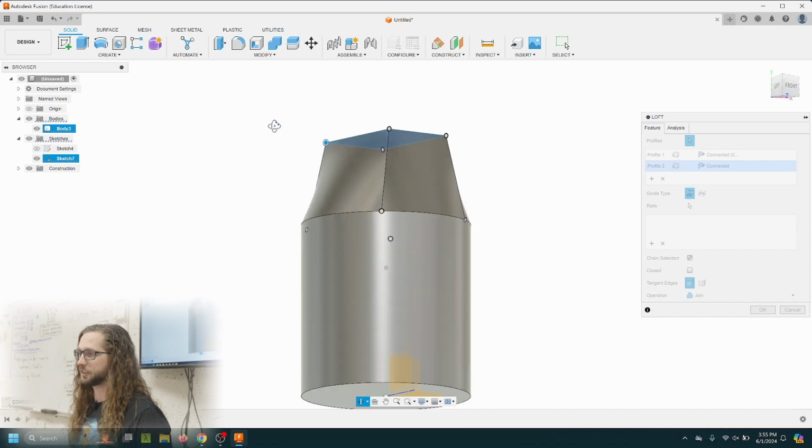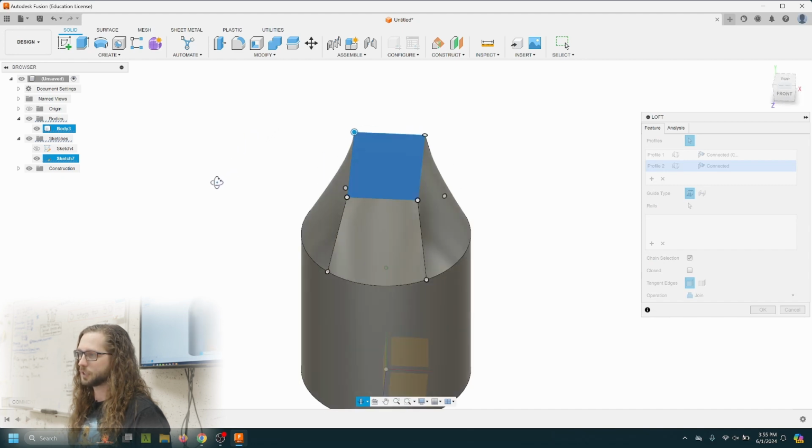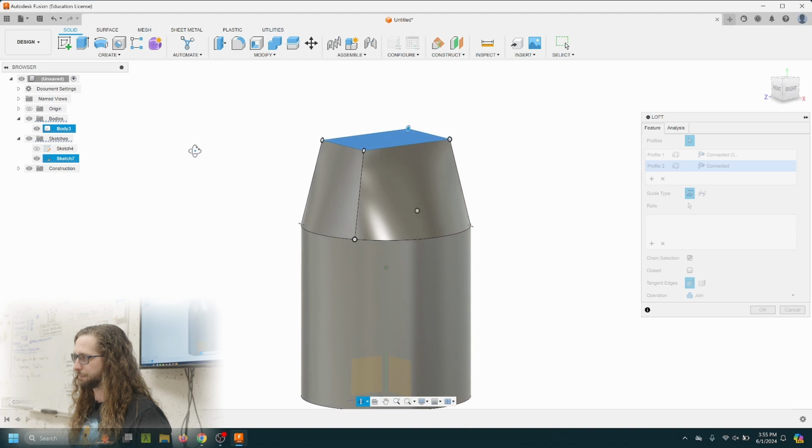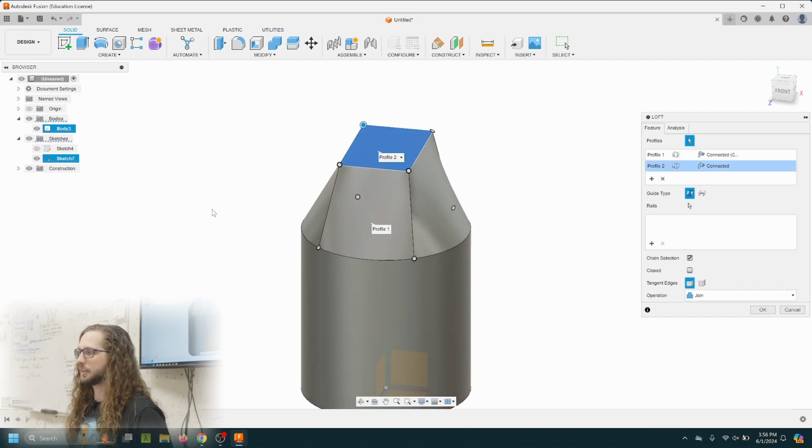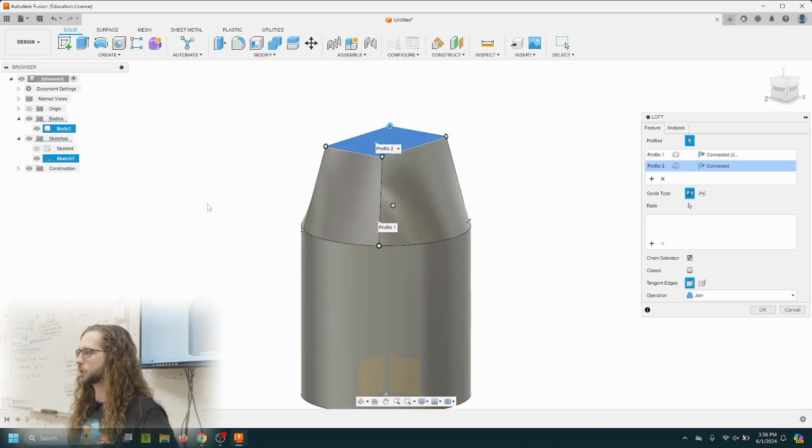So you'll notice it's created these compound curves attempting its best to connect a round circle to a square. It doesn't have to be a square. It, again, could be one of those arbitrary curvy objects. And there's some additional things that you have control over how it's making these connections. When you do a loft, Fusion defaults to this connected state, which is basically what is the shortest path that I can take that makes a smooth curve between these two-dimensional objects.